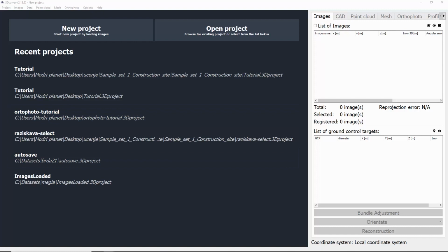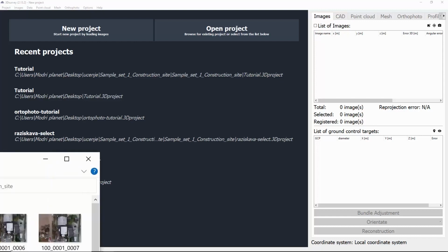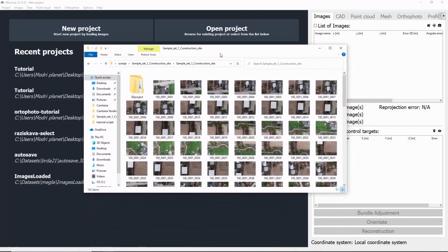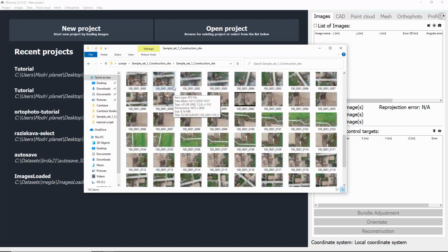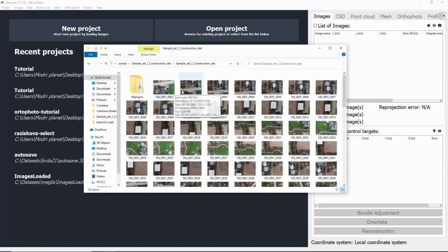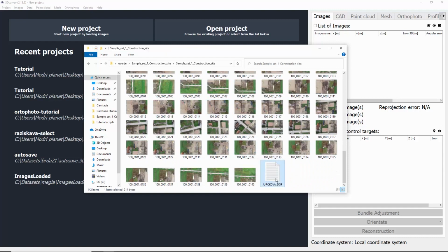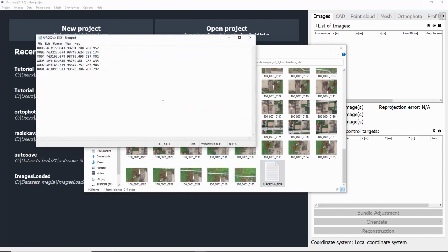In this video, I'll be showing you a basic workflow from images to orthophoto. First, I would like to show you the basic results we get by flying the drone over the area. In this case, we were using Phantom RTK, which made 140 images, overlapping each other 70%. In the end, we have a GCP file containing 6 ground control points measured with a GPS instrument.